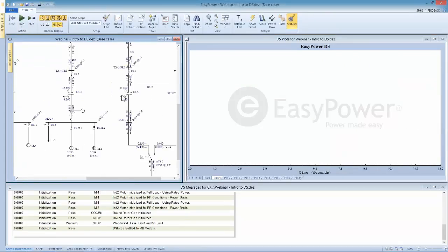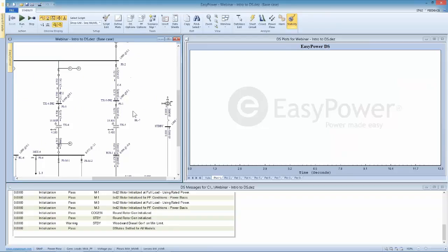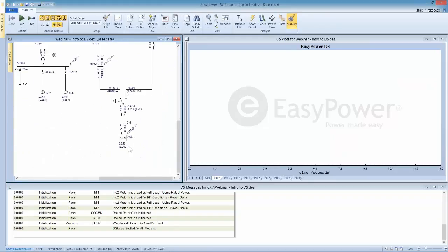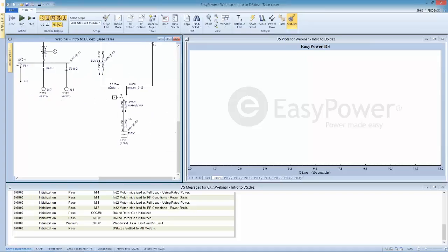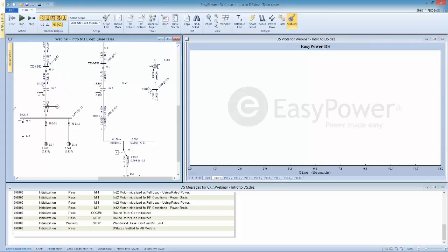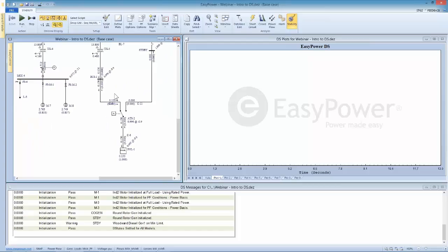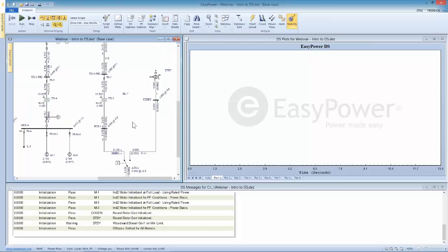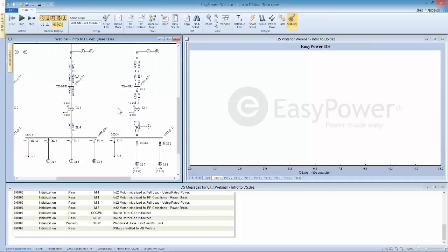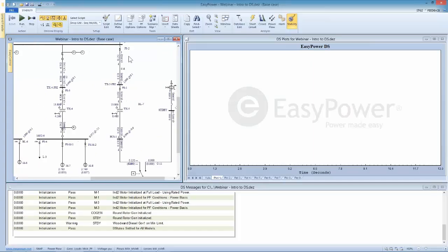So the next example we have set up is how does the ATS respond to a system fault? So what we've set up for is the ATS to respond to a loss of power and switching over to the standby backup generator, and there's really no motors involved. It's basically a linear load, but again, it's a function of the double click feature. We don't even need a script to do this.